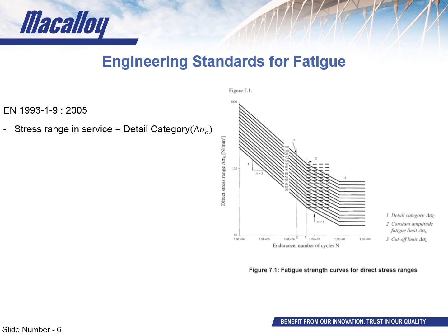Now stress range, which is a key term you're going to hear me saying an awful lot today, is the difference in stress experienced by the material as the load increases and decreases in its fatigue cycles. Once all of the structural checks have been performed and you've managed to ascertain the load range that the bar is likely to experience in service, this load can then be transferred into a stress range.